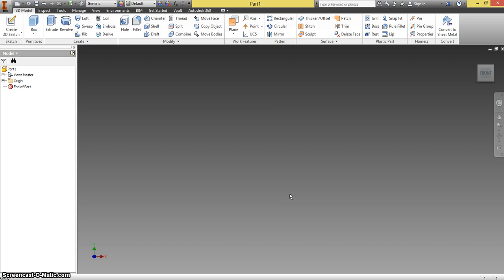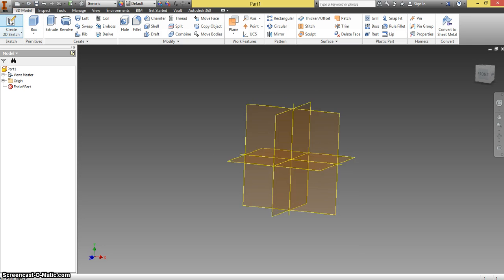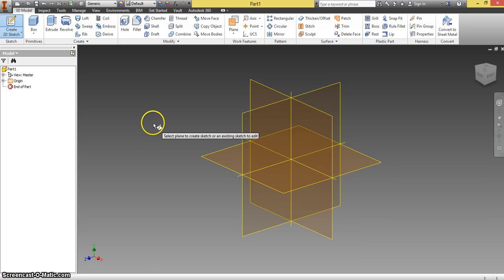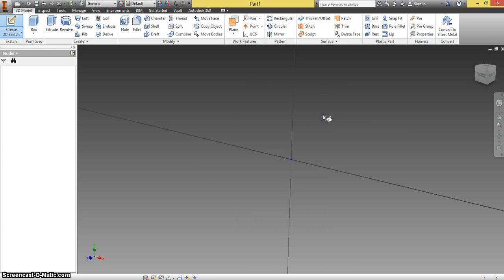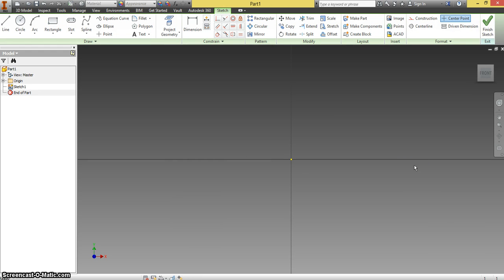First thing we're going to want to do is create a new sketch so that we have a place to draw. So we have to go up to our 3D Model tab, Sketch. There it is, waiting to select a new plane. I like this XY plane because it just comes right toward me. It doesn't twist around, turn, or anything. Then we have to look at the drawing that is on our sheet, and we have to create that thing.